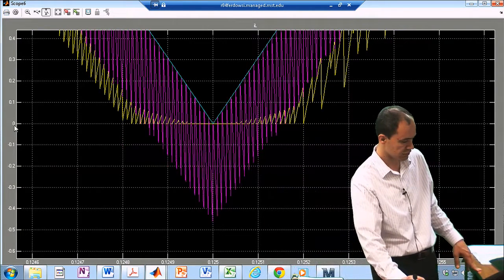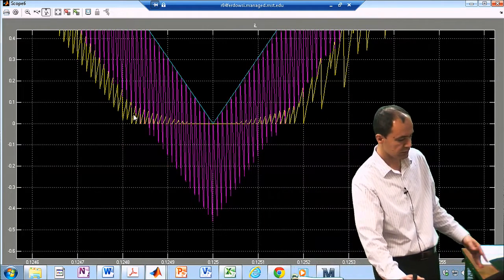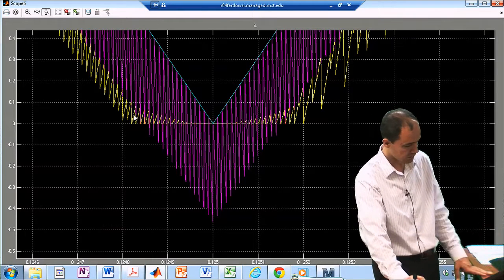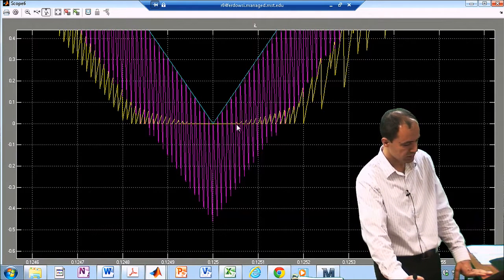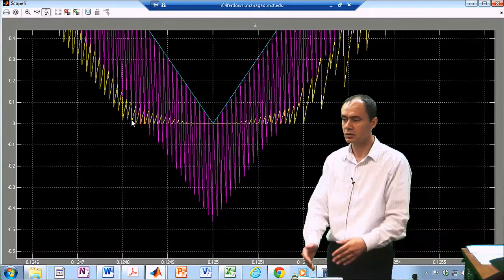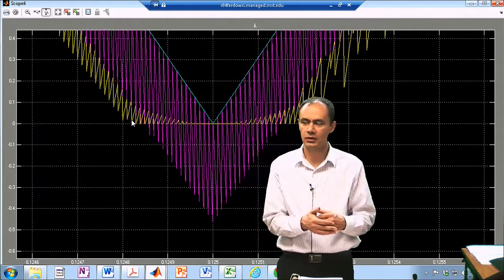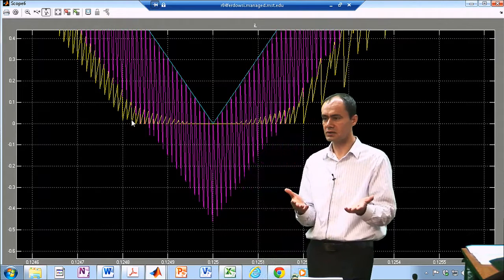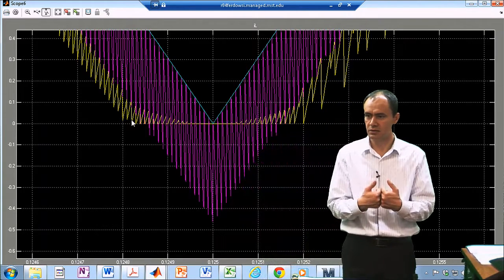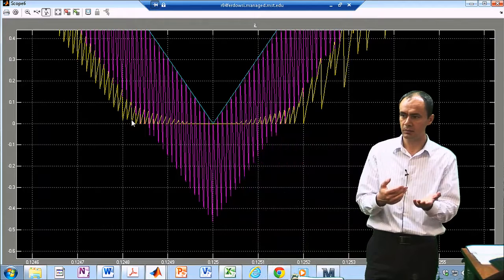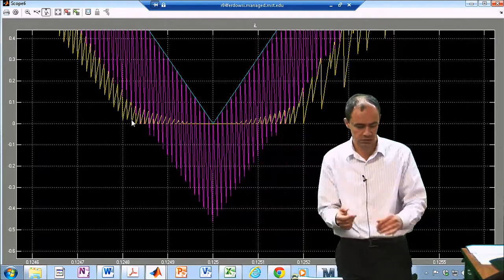So this is actually our 0. But the inductor current cannot get negative because of the diode, so it remains at 0. So you can see that here we have an error which is called zero crossing error. If you want to eliminate this error, you have to basically get rid of the external ramp. But if you get rid of the external ramp, then you have a problem in terms of subharmonic oscillations.